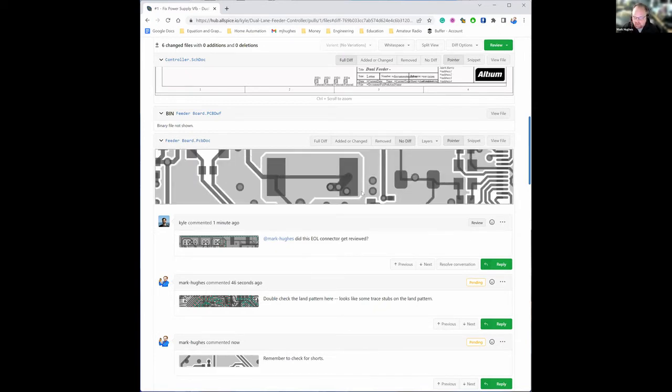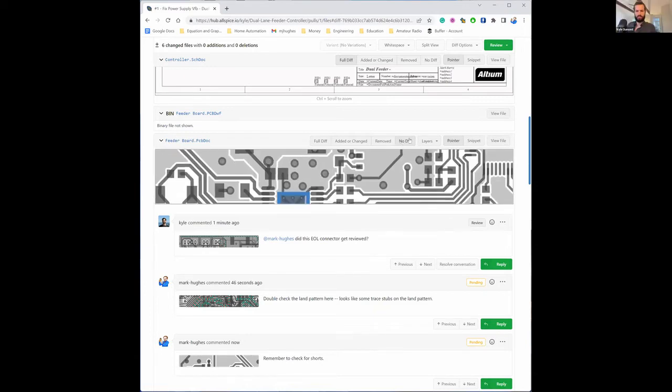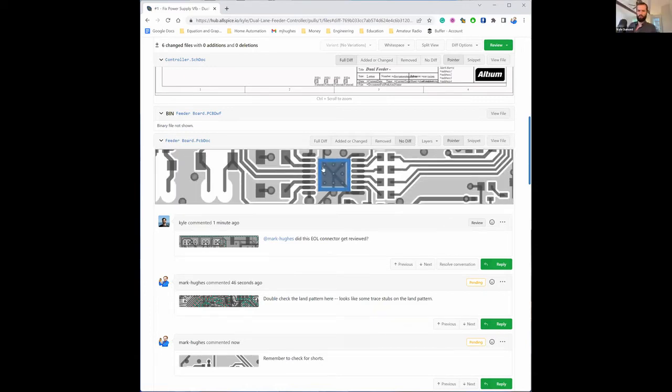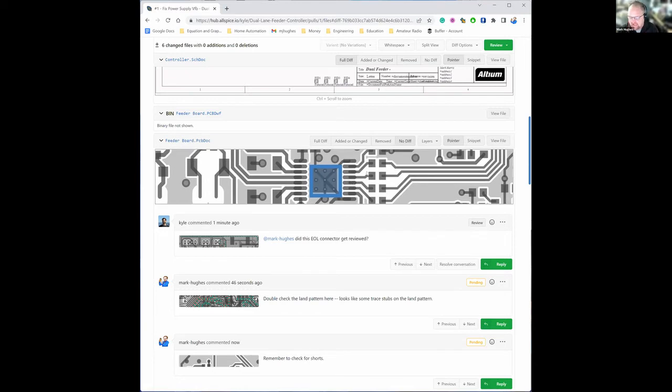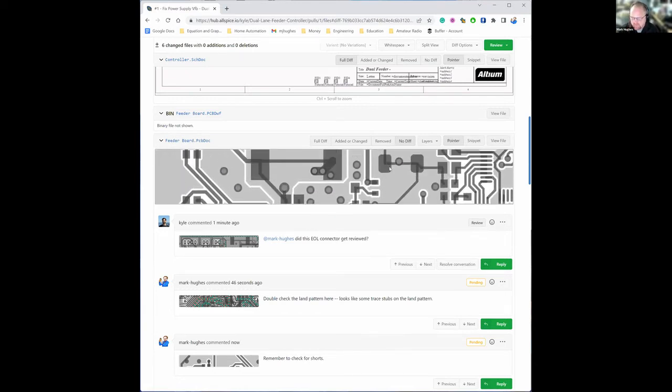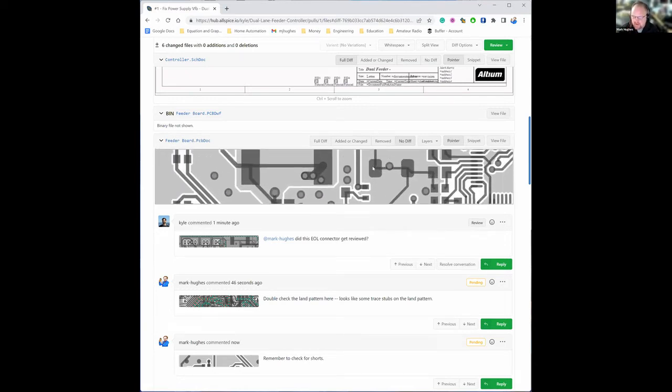So that's like a paste mask, Mark? That will keep the solder from encroaching on those vias. Is that the idea? Yeah, it's not a paste mask, it's a solder mask. Solder mask. Yeah, it's exactly that. It just creates a bunch of dams with the LPI, the liquid photoimageable solder resist.